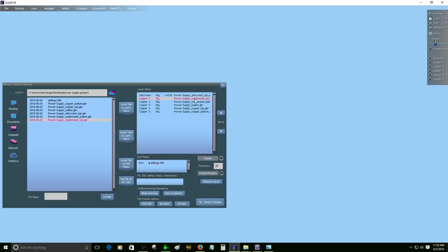The second one, it says solder mask top. It's already correct, so we need to change that to solder mask. The other one is solder mask bottom. We're gonna change to bottom. This is outline, border outline, and then I type here 850. Let's go to change this to 850. Set equal spacing. There you go.